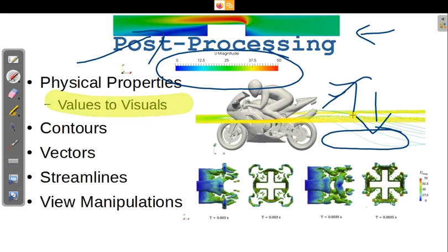So this will have crazy structures. On seeing this, you will be able to understand how much fluid is rotating, in what direction, and with what magnitude. You can superimpose velocity magnitude. On the right side, I have a superimposed velocity magnitude over vorticity. So you can do all the manipulations you want, and you can make your solutions as attractive as possible. That's the beauty of CFD.